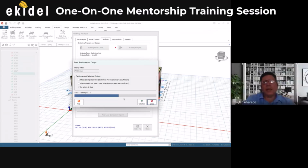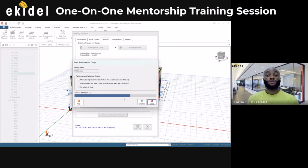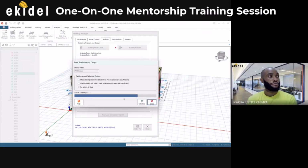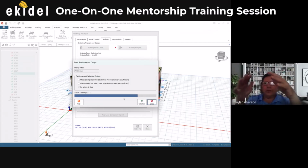Yeah. And so this beam design, it automatically puts it on all the four. Even if you had a roof, you don't have to. Yes, it will design for all the stories, all the floors. And it would automatically angle it with the roof. Yes, it does that. So you don't need to create a specific load on the roof.